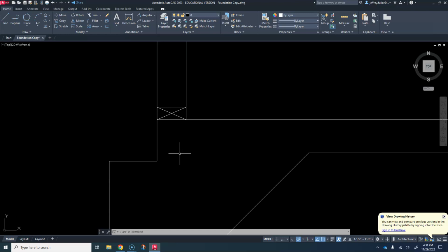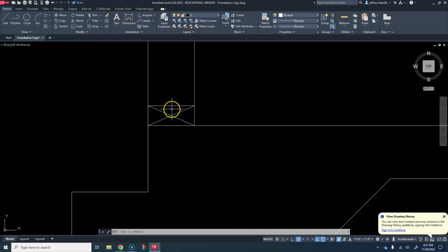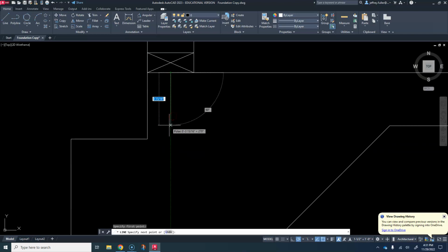So you're going to have 7 inches buried in the concrete, 3 inches exposed above the concrete. How do I draw that, and how do I get it in the center of this sill plate? Okay, this is how you get it in the center. You start with a line, and you just go right up here to this cross section, and you're just activating the geometry as a reference point, and you're going to pull your cursor down. And right here, when you get to the top of the concrete slab, that's when you click on your mouse and draw the line 7 inches into the concrete.